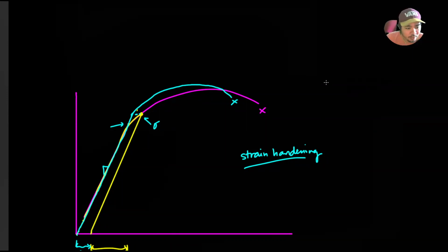Okay? Nico asks, is strain hardening the same as cold working? Yes, it's the same in ours. Strain hardening just describes the mechanism of how our metal hardens or strengthens. But it can also be described as the process of deforming metal to increase its strength. So in some cases they can be used interchangeably, but in some cases there are certain scenarios or terminologies where only strain hardening can be used and not cold working. But in general, you could say they're almost interchangeable. Okay?